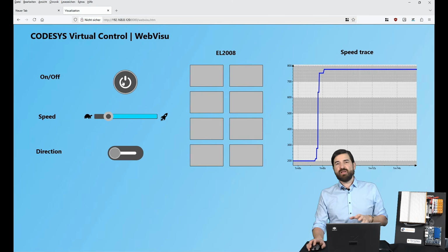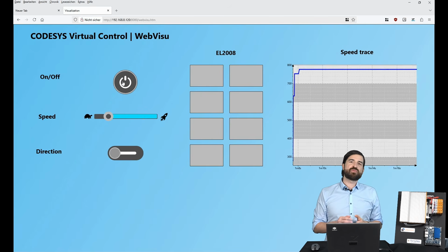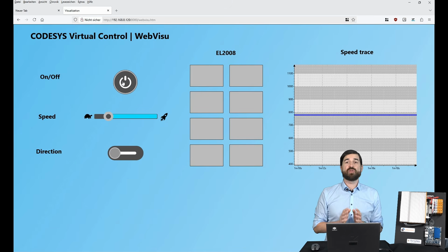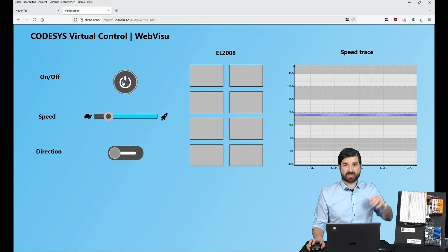So we can see that just in a few steps, we've gone from 0 to setting up a new virtual PLC and getting an application, complete with fieldbus communication and visualization, up and running on it. To conclude the live demo, I'd like to stop the container instance of our PLC to show that CODESYS immediately loses the connection and also stops the application, including web visualization and IOs immediately.